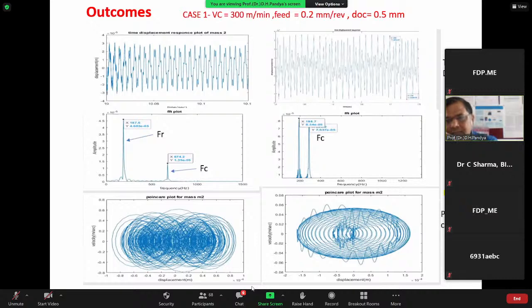As we can see here, using the FC without SIM, the chatter frequency is at roughly these values, and that was significantly reduced with SIM. A more interesting outcome we observed with the Poincaré map, because without SIM the system is more chaotic at low speed.